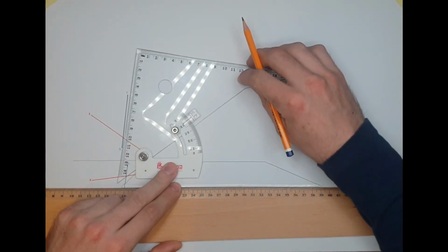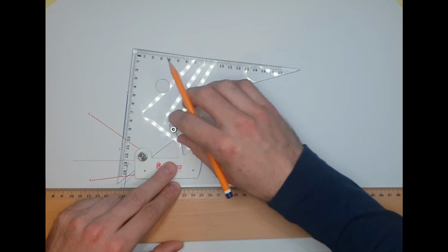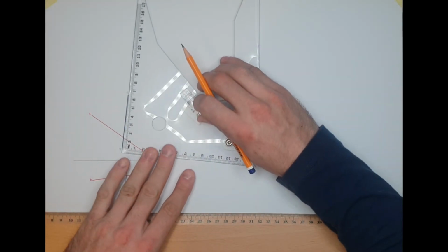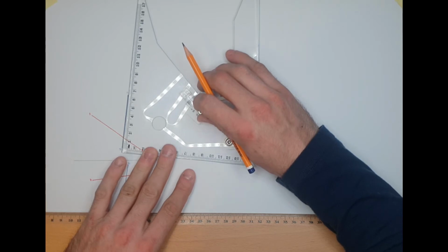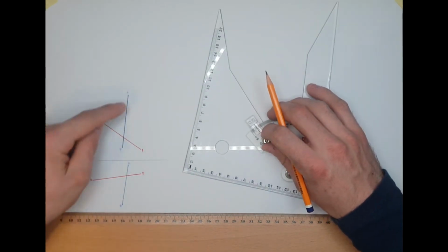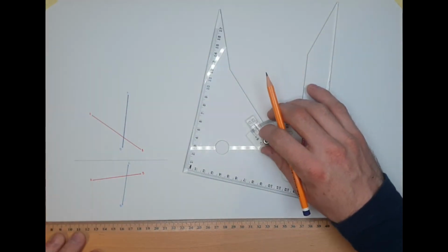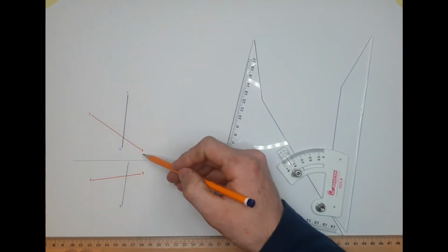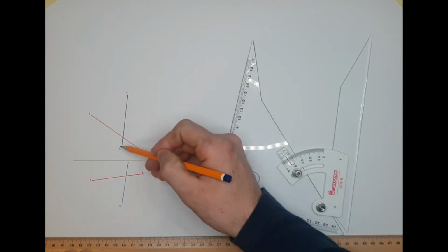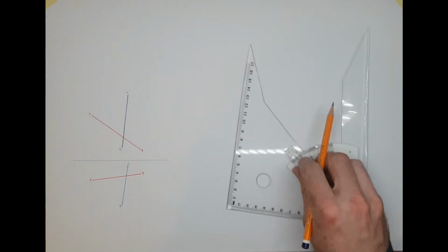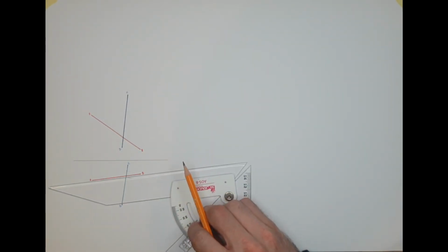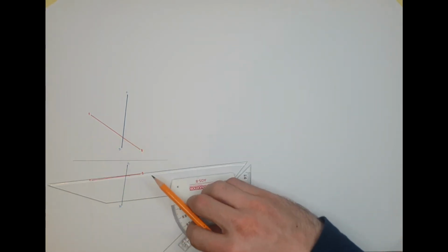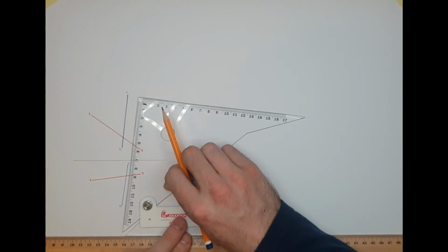I made that blue line 7 degrees of an angle, and it is approximately 62 millimeters long in total, and it just appears to cross right there. Down in plan, then I projected down the end of A and B and the end of C and D. The line AB, I think I made that about 7 degrees again, just crossing over. And CD there is an angle of 9 degrees.